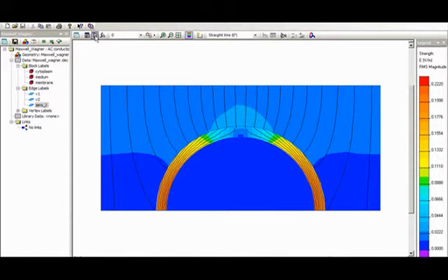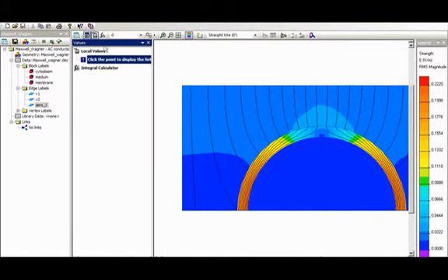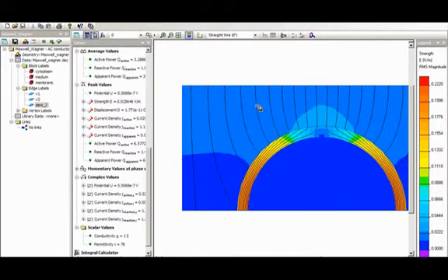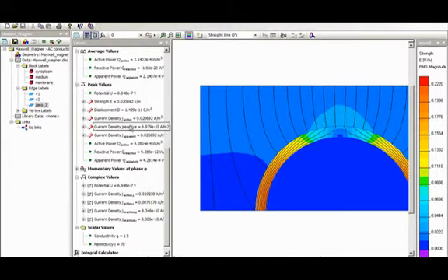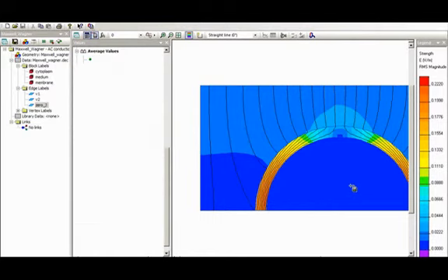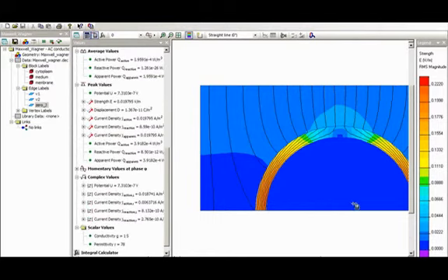If I just want to look at these components at a particular point in the model, I can choose this tool here and select different points. So I can use this value selector, and I'll make this a little bigger to illustrate. These are the active, the reactive, and the apparent current densities at different regions here, and you can see that they're much smaller inside of the cell than in the external region. This is 10 to the -7 compared to 10 to the -2.